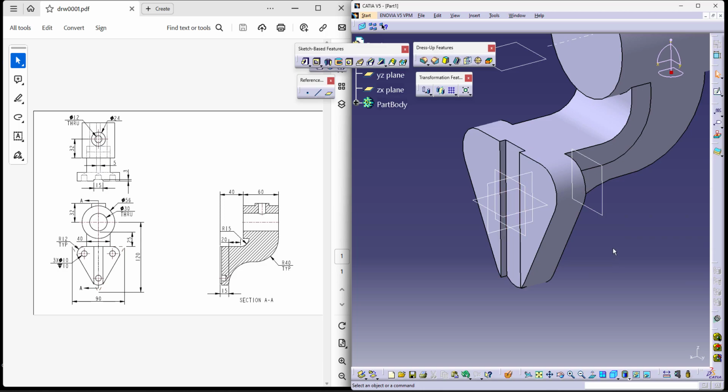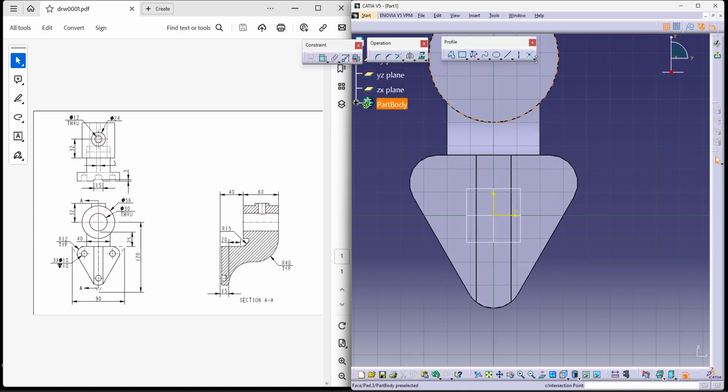Now we can start drilling our holes slowly because we do have a hole on this face. That's why I have done it this way. Now let's try to take a sketch first to make our points because all are concentric. So I'd like to make a point and then maintain concentricity with this. So I can mirror this point onto the opposite side, but I need another point at the bottom. So let's try to make that point at the bottom and then maintain concentricity with this as well.